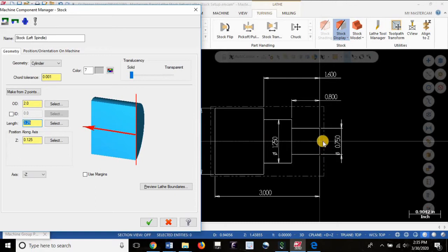So that indicates the space between this gray dashed line, which is your rough stock, and this solid white line, which is your finish size. So if you're having a difficult time determining how much material you should remove, maybe as a default you like to do 50 thou on your first face, that's fine if it's suitable for that application. But just to make things easy to help you decide when setting up a job, most times I like to take equal amounts of material from both faces in two separate operations.